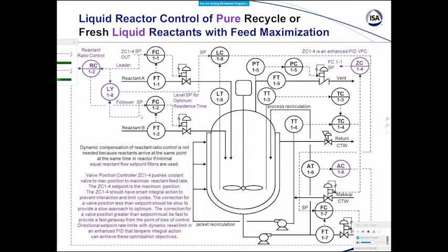Now, that may seem okay, and that's commonly stated as the goal, until you think about pressure disturbances. You have the same set point in flow, but now you've got to deal with pressure disturbances. I mean, that's one of the tasks of a flow controller, right? To deal with pressure disturbances. If you slow down the tuning of it, you reduce its ability to compensate for those pressure disturbances, or if the valve position isn't quite right.